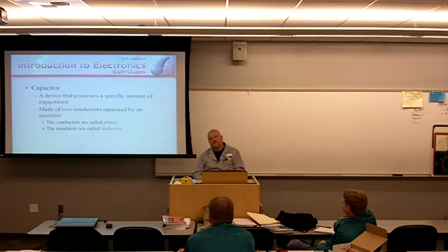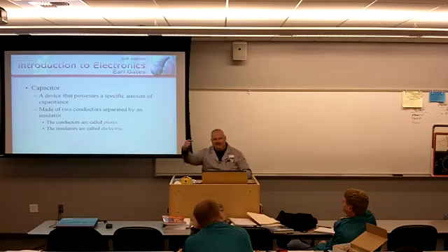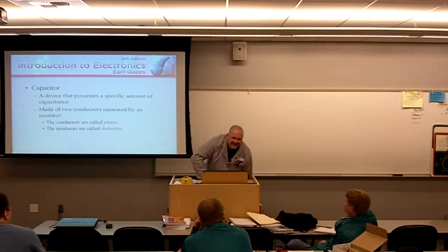The old flat TV antenna wire from the 1950s. Yep. And that actually, believe it or not, that style of twin lead antenna cable, it was some of the most efficient. When properly installed, it had higher efficiency than coaxial cable. The only thing is people would get that nice ribbon cable, and then back in the day, growing up in Connecticut, we had aluminum windows, and you'd route it through the window and then slam the window down on it, and there goes any advantage that you had.